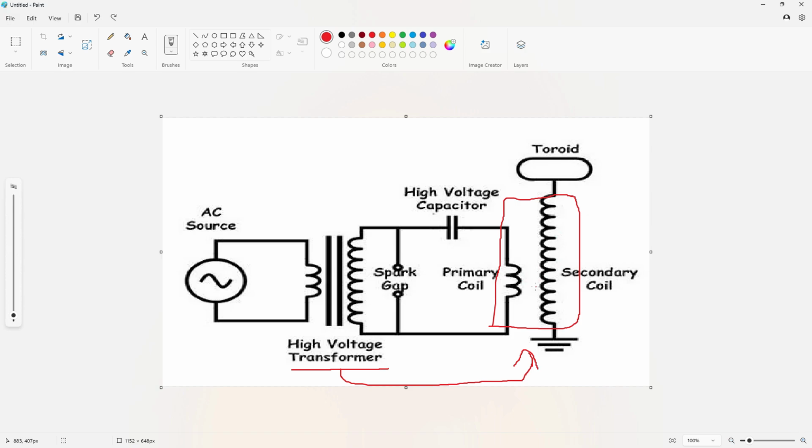So air core transformer, it has a primary. This can be kind of misleading, because this primary is not like the winding on this primary. Again, this is an air core transformer, so what happens on the Tesla coil, and I'll show you this in another picture, is the primary winding on the Tesla coil side is usually some kind of winding that sits at the base of the Tesla coil, like this, and then the Tesla coil itself is in the center. Okay, and then it would have the toroid on top. That would be your Tesla coil in the center, and then your primary winding would be around it.